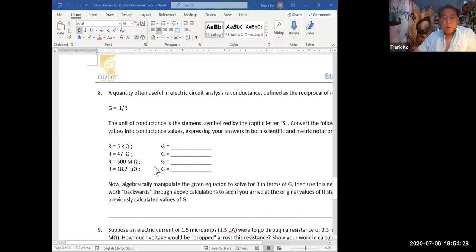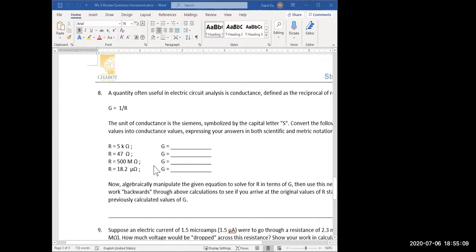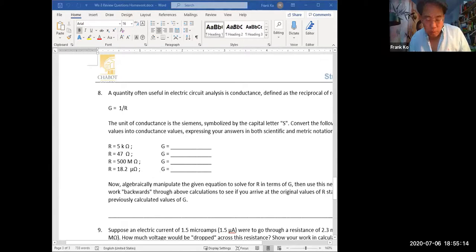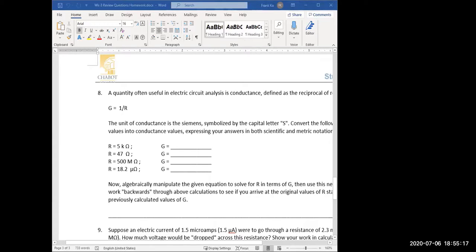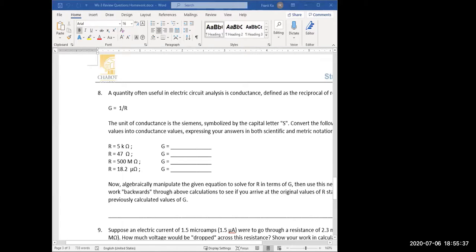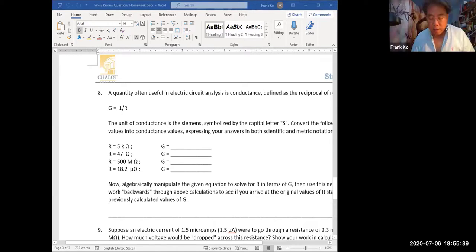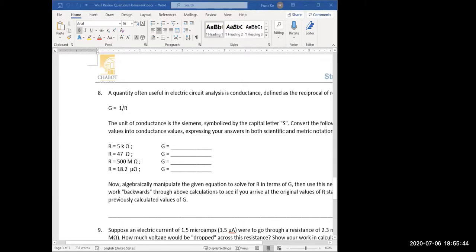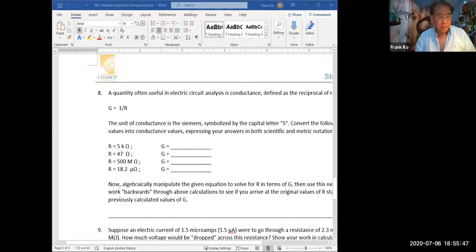The question is whether you're reading the numbers correctly. I got 54.9 on the calculator. Okay, so those three things are correct, and we want 2 digits after that decimal point. So 54 point what? 95, followed by what engineering prefix? Kilo. Kilo is correct. And what units are for conductance? Siemens.